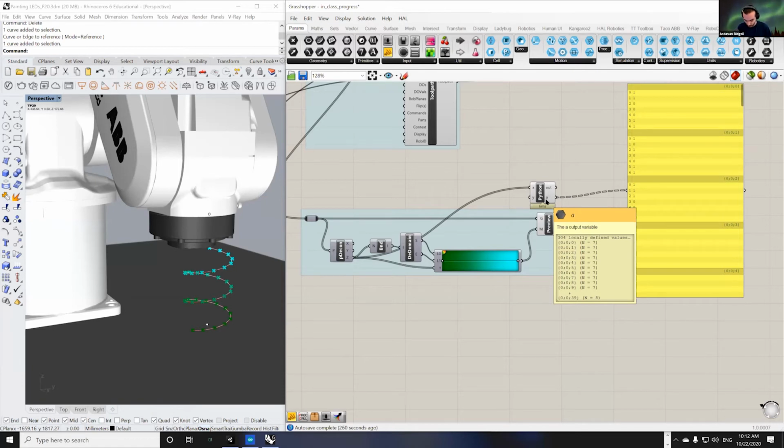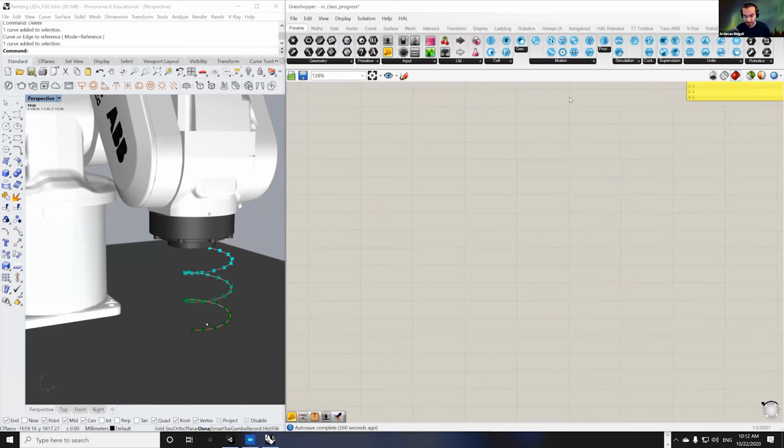So basically, what I'm going to do here is to define a bunch of move commands. At the end, it's going to be, for example, move J. So the robot goes to that target, and then it should do a lot of set and reset for DOs.